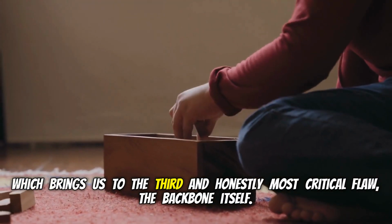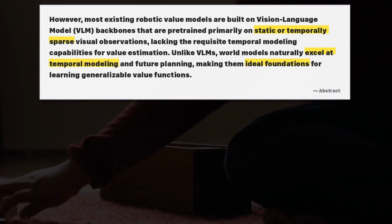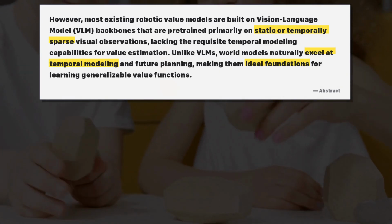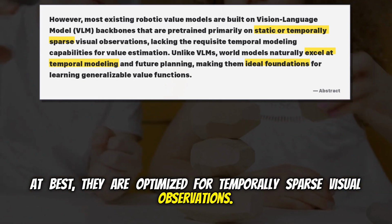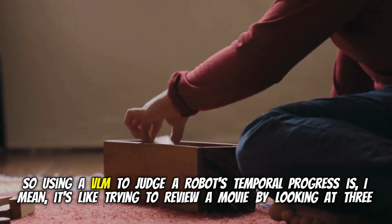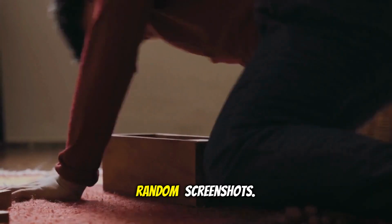Which brings us to the third and honestly most critical flaw, the backbone itself. Right. Generalist models today are built on VLMs. And VLMs inherit internal representations that were optimized for static images. Right, because that's what they're trained on. At best, they are optimized for temporally sparse visual observations. So maybe looking at a frame from the beginning of a video, one from the middle, and one from the end. So using a VLM to judge a robot's temporal progress is like trying to review a movie by looking at 3 random screenshots.